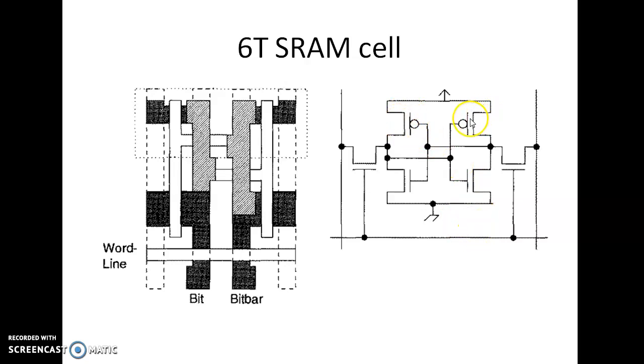Resistors are replaced with a PMOSFET because a resistor needs more fabrication area, and fabrication is complex, and if you want to change the resistance completely, you have to refabricate everything. And the advantage of this PMOSFET is that simply by changing VGS and VDS, you can change the resistance according to the requirement.